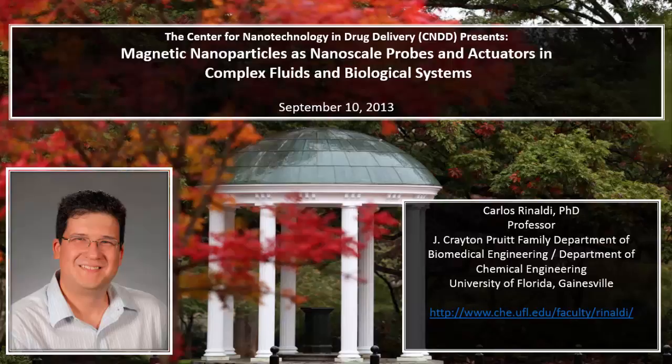And the reason why there's disagreement here is that for this sample, there was quite a bit of excess free oleic acid, and at that temperature, it started to crystallize, and that led to some aggregation of the particles and the deviation in terms of the behavior. But the important point is that we can make quantitative measurements of the viscosity using this technique in simple fluids.